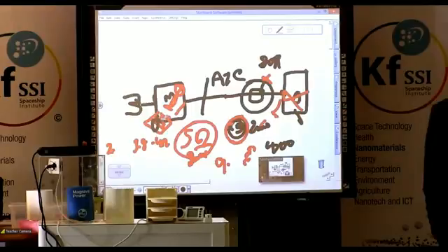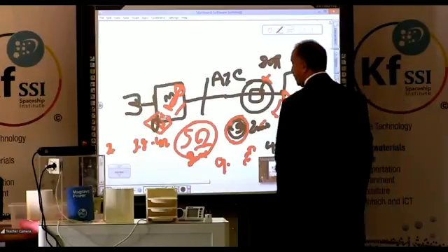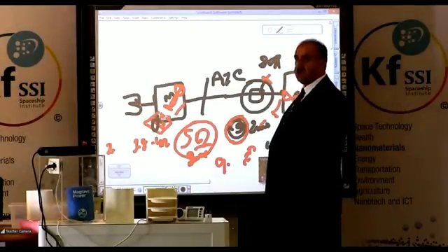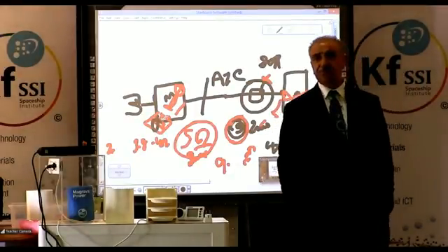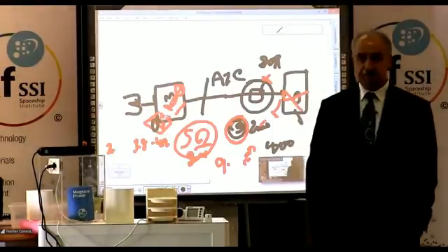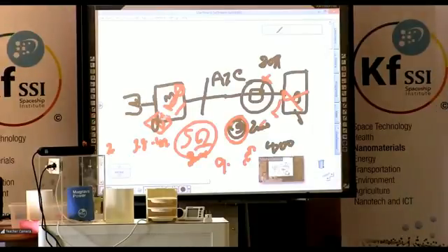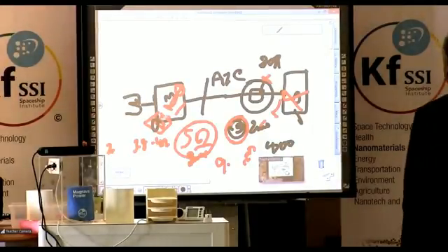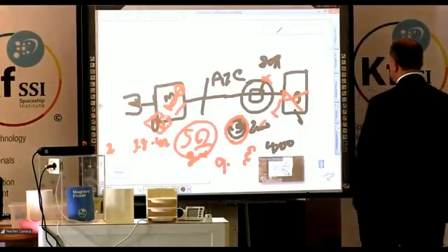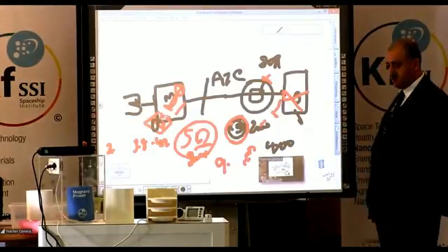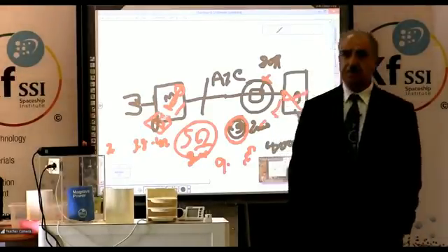You need a thermal circuit breaker that measures not the current, because which current are you going to measure, the DC which is flowing or AC? So the easiest thing is a temperature circuit breaker. It's just the heat. As it reaches 55 degrees, the circuit breaks. It's not a high current, it's just a temperature measurement. Okay, that's good information. Thanks for that question too, Eugene. They cost less than 50 cents, very cheap pieces.